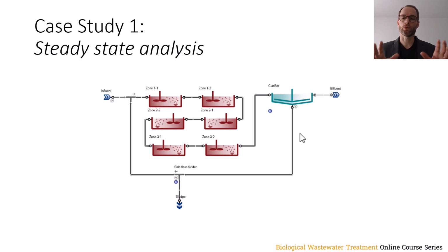And then we input directly the reported airflow into the bioreactor using an assumed diffuser density taper. And we were able to simulate a DO profile that showed about 2 milligrams per liter of oxygen in the second and third pass, and then around 1 or less than 1 milligram per liter in the first pass, which seemed to be more or less representative of what we might expect to see in a full-scale system where they are instrumenting and measuring DO in the third pass.